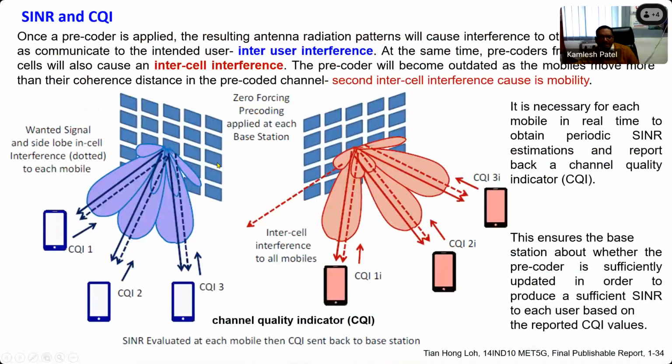At the same time, when the signal is being transmitted back to the user element, for each user the MIMO is able to change the direction of the beam as per the location of the user. There is a possibility that the solid line is coming from the main intended user, while the dashed line represents signals from the massive MIMO system which is actually meant for the second user.